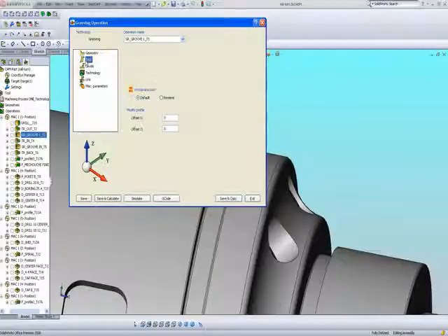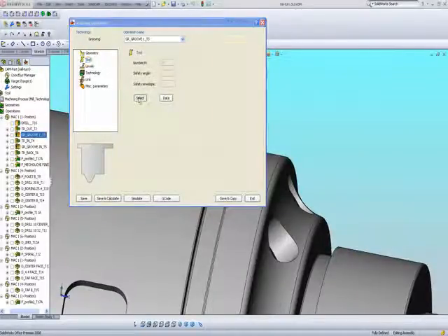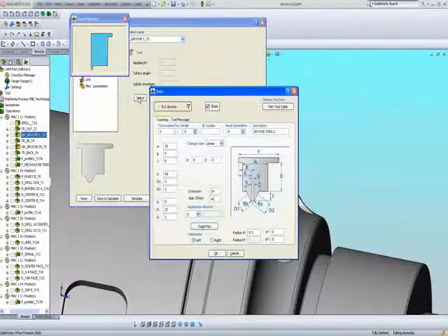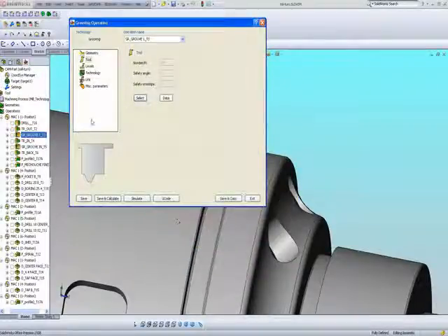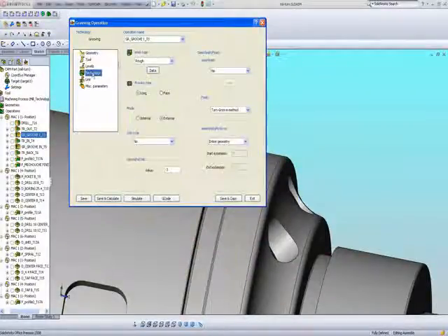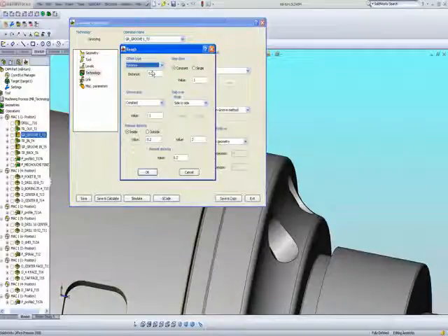The tool is a tool specifically for grooving. In my technology, I'll have my working area, my work type as rough, and the data area I have an offset, and my step over will be going from one side to the next side.